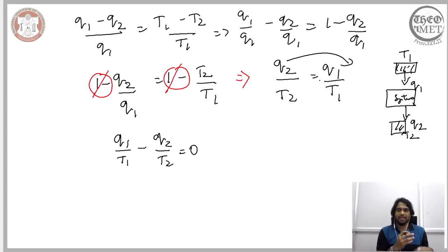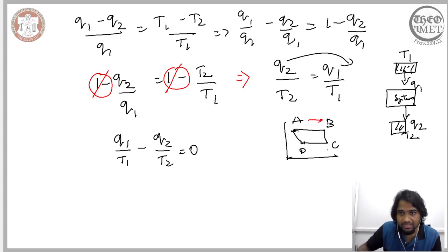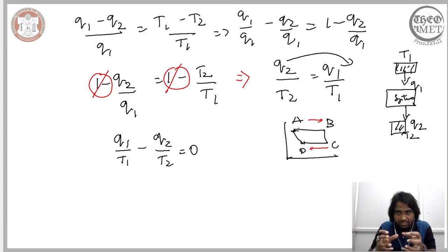So essentially this is the Carnot cycle. If you recollect, we begin here, move to C and D, and finally A. So the heat transfer is confined to AB and CD alone. In BC and DA, this is the reason we insisted on describing these processes as non-adiabatic isothermal and adiabatic non-isothermal. So AB is non-adiabatic but isothermal, and BC is adiabatic and non-isothermal.